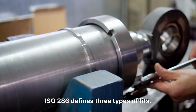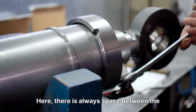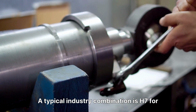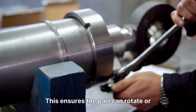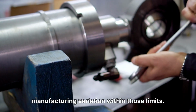ISO 286 defines three types of fits. First, the clearance fit. Here, there is always space between the hole and the shaft. Think of bearings or sliding parts. A typical industry combination is H7 for the hole and g6 for the shaft. This ensures the part can rotate or slide freely without jamming, regardless of the manufacturing variation within those limits.